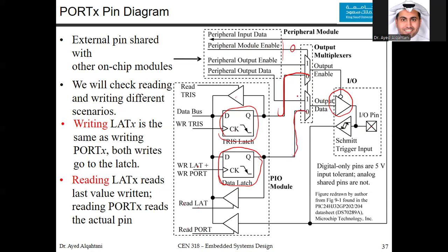If you want the other peripherals, then you will choose 1, and it will give you the peripheral output enable based on whatever functionality was multiplexed with it. And the other feedback here will be used in the peripheral module. Our focus here is the GPIO. So we want to understand the TRIS, the LAT, the port, and also what's happening here.